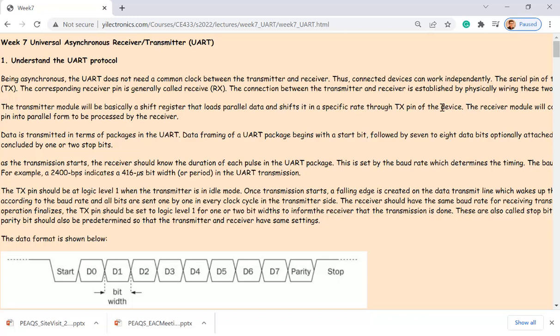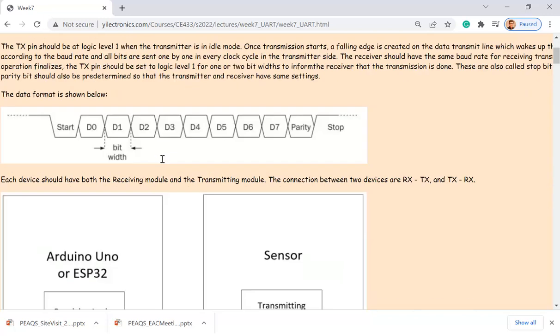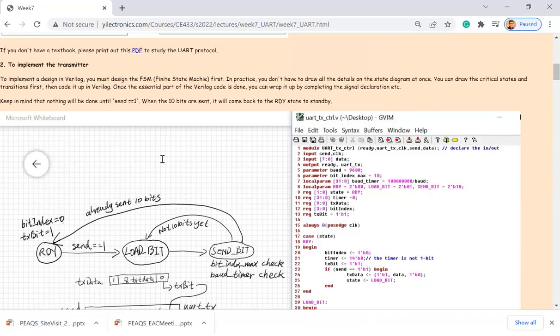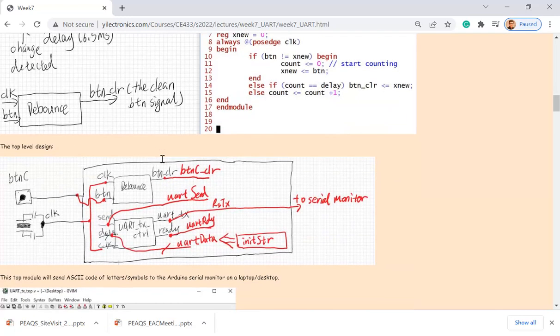And communicate with an embedded system instead of a laptop. So you have your Arduino here, a level shifter to step down the voltage to 3.3, have the FPGA with a UART module on it, and try to send something to the Arduino and display it on anything. It doesn't have to be a laptop, it can be something else. That'll be another really interesting test as well. But we don't have it this time. So these are all the tasks you are supposed to work on. Just spend the time on it. No questions?